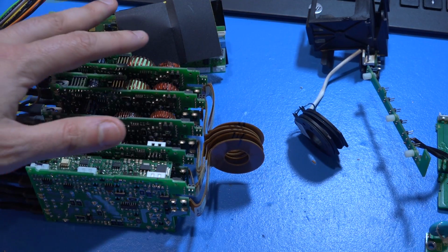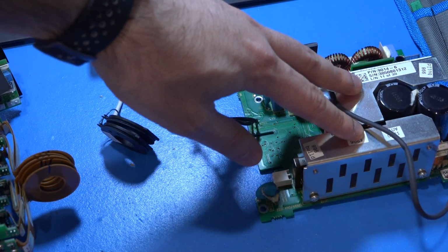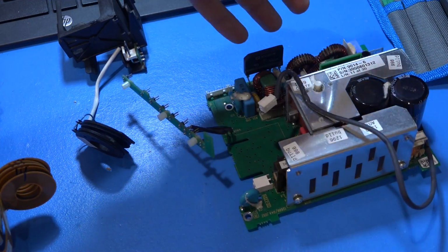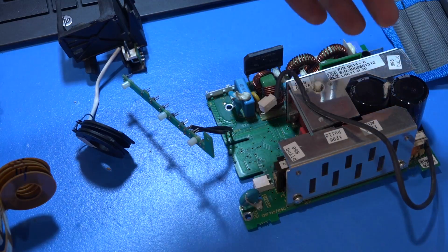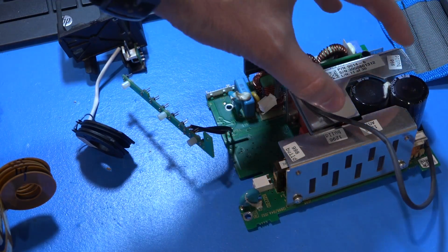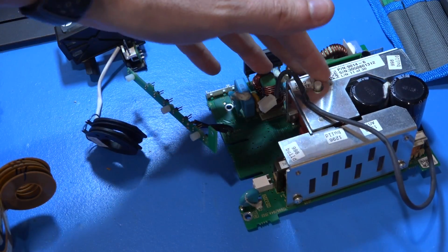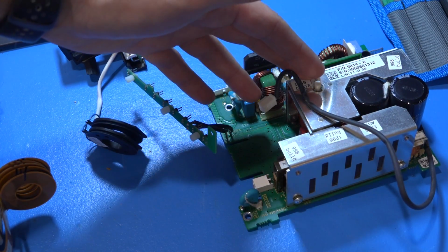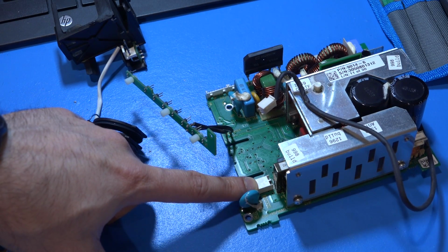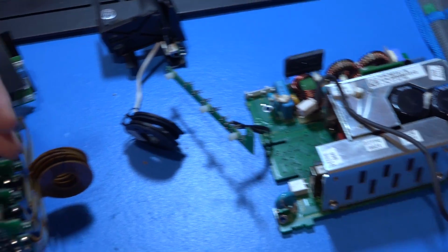So how do they do that? Well, it turns out that what they do is they keep the primary side of the power supply essentially constant, at least as far as I can tell. It is constant. So it's got the rectifier, the filter, the switching side, and the capacitors, and a whole bunch of other protection circuitry here and there, the first side. And then there's some feedback voltages for protection, again, to turn things off if there's something wrong. But the transformer primary side is driven with this connector, which means that they can plug in a transformer in here and create primary to secondary connection.